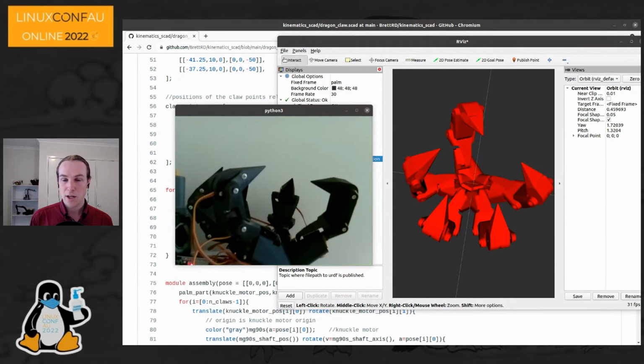You can encrypt it, and SROS, Secure ROS, basically provides an API to manipulate the DDS security layers. All DDS vendors implement a security profile. It's just a mandatory aspect of the minimum DDS spec. So you can configure that, but you end up locking nodes into their one lane.